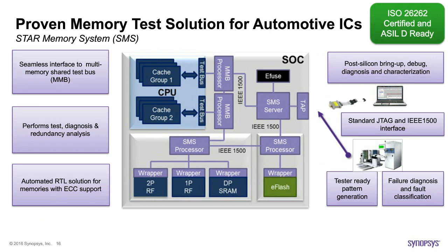This is my SoC. I see in it numerous types of memories, whether they are SRAMs, ROM, register files, caches, embedded flash, content addressable memories, and so on, all of which are sitting to do their function in different blocks or subchips. But while doing their functionality, we need to take care of their test. So doing BIST with memories is something that has been done for a long time. We have done it for the past 25 to 30 years. Every single memory gets self-tested, which is nice. They get repaired as well for the last 10 or so years, which is also very good for yield purposes.